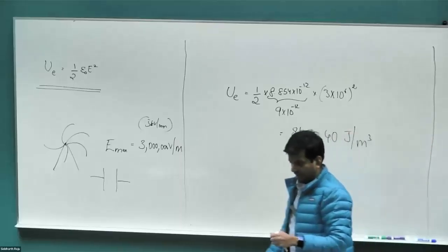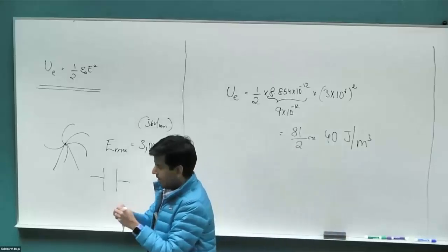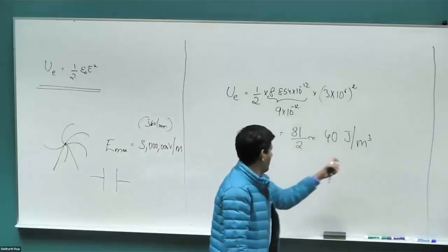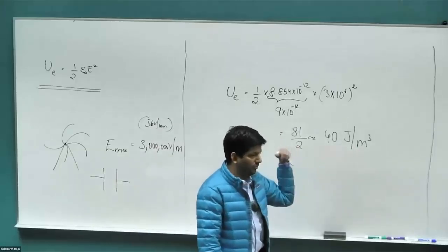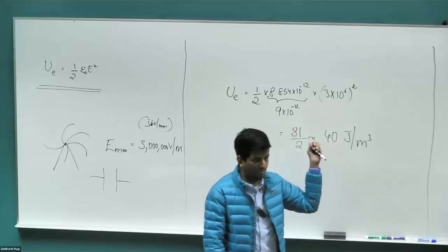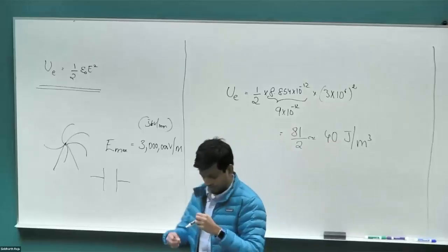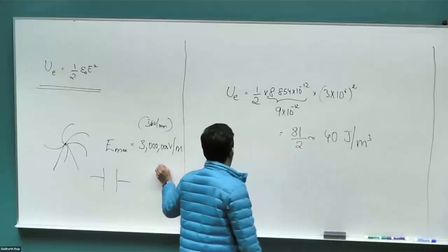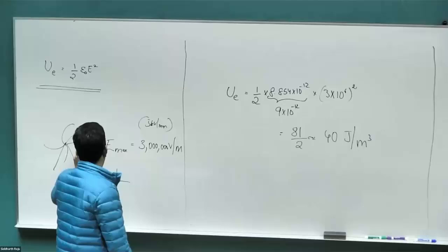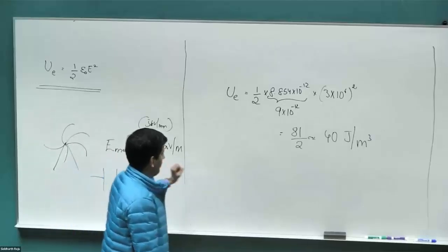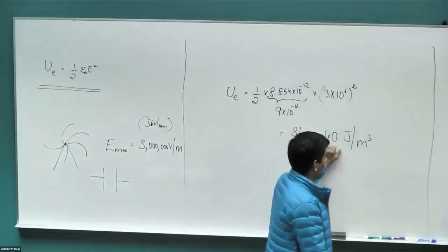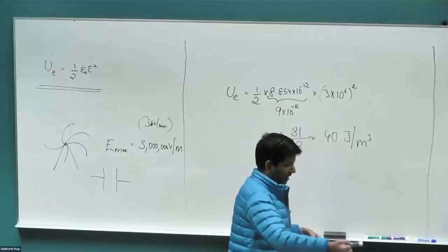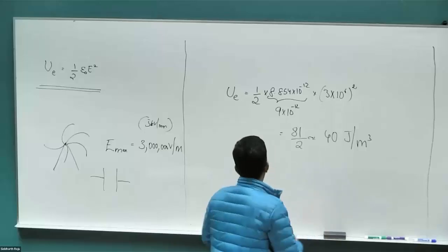So if you create some kind of planar capacitor such that the volume within the capacitor is about a meter cube, the maximum energy that can be transferred through the air gap medium is about 40 joules, above which the medium itself will start to puncture and collapse. So this is the maximum we can do with an electrostatic motor. We definitely do not want to exceed this for a day-in day-out operating motor. And as we'll see in just a minute, this energy is extremely trivial. Not at all comparable to the motors that I have on the tables or even a simple motor that's in your watch.